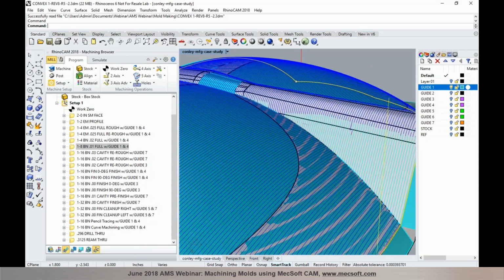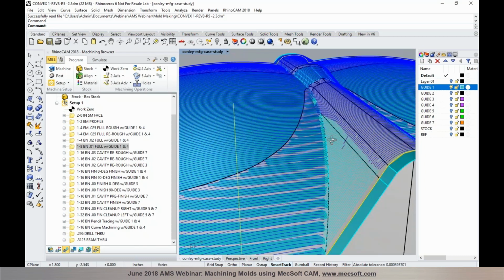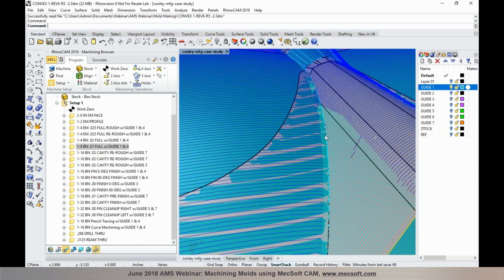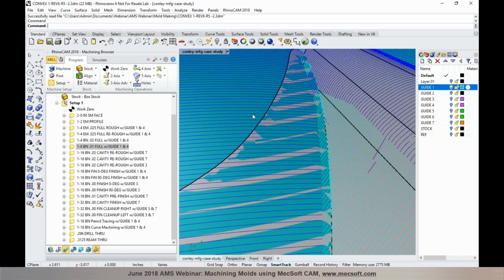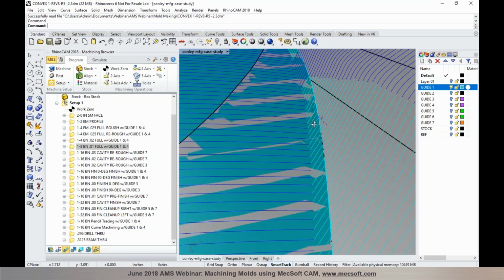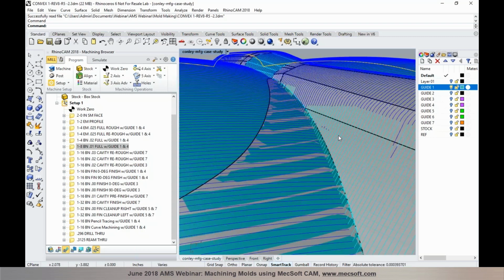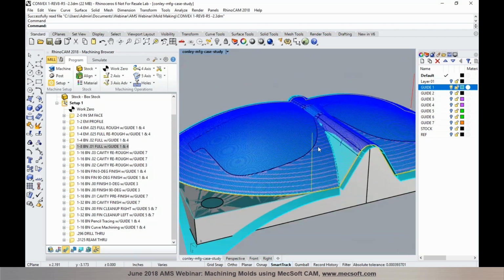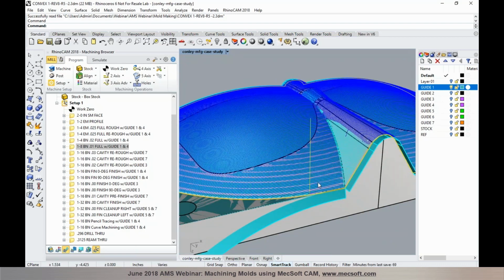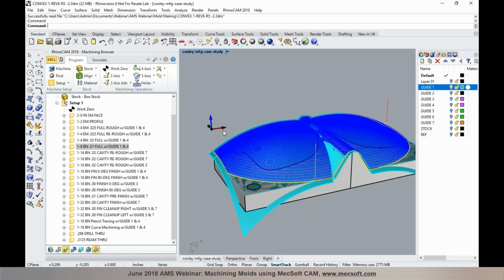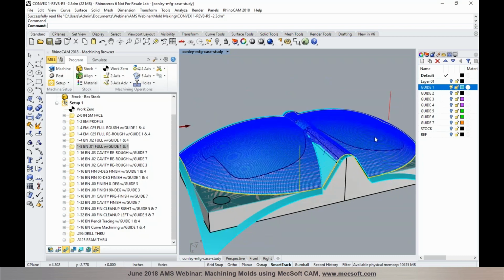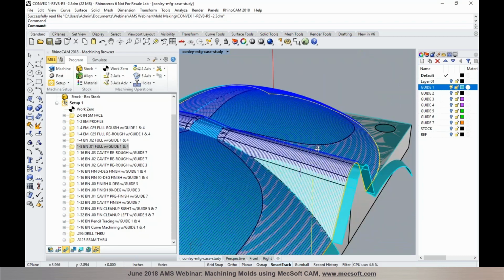And you can see the tool path in here also has a very nice transition in these areas as you go from these steep sections down to the sculpted areas here. Look at the nice transitions in the tool path, and also you can see the arcs being fitted to the tool paths. So you can have arcs being fitted in all the 3 principal planes, which is your XY, XZ, and YZ planes. And in this case, you can see arcs being fit in the G18 plane, resulting in a very nice cut motion in here.